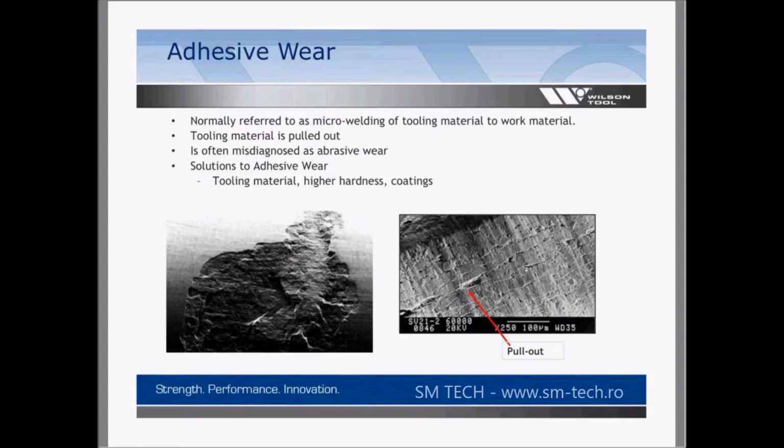So again, you know, changing the material type, going to a higher Rockwell on that, and even coating that punch will help with that. The coatings are a big thing here to help prevent that adhesion as well.